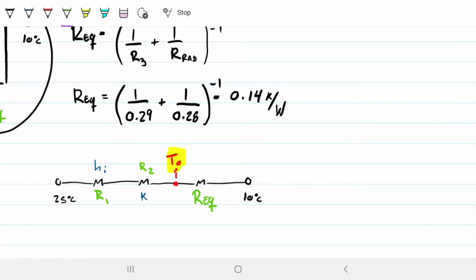So we're combining both the convective and the radiation disguised as a convective in one, and this is going to give me a new sum of R's. And this sum of R's is going to be the 0.14 plus the 0.016, and then the 0.01011, and that gives me 0.25622, 0.256 is fine.